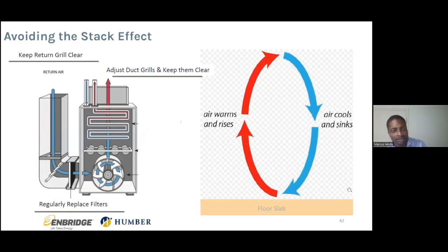Now, filtration, in terms of your furnace and your ventilation system, filtration is very important. So one of the things that you want to do is make sure that your air filters and your air filtration are up to par as well. You want to make sure that your air filters are clean. A little bit of a caution here, and this might have come from when the air quality was not as high as it possibly could be, but you don't want to go too fine with your filter spec, because too fine means that your furnace has to work harder to force that air through, and then on top of that, it's going to collect more and more particles.